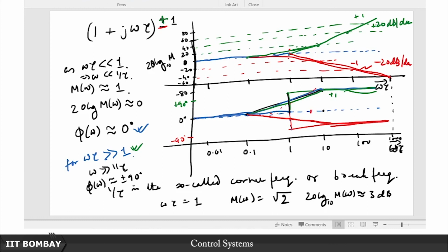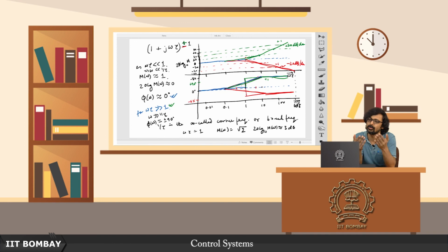It is just a matter of which approximation, whatever floats your boat. At the end of the day the asymptotes do not intersect in the case of the phase plot. So there is a discontinuity. You can draw the discontinuous asymptote like I showed earlier, that is a valid way of drawing the asymptotic Bode plot.